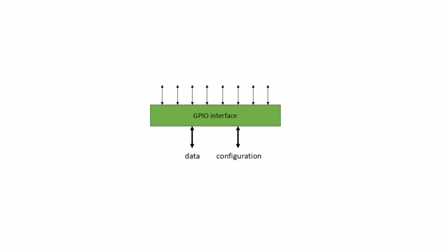Many microcontrollers provide general-purpose I/O or GPIO interfaces that provide a simple way to do easy interfaces. Each general-purpose pin can be programmed independently as either an input or an output. The pins can be configured by writing to the GPIO configuration register.